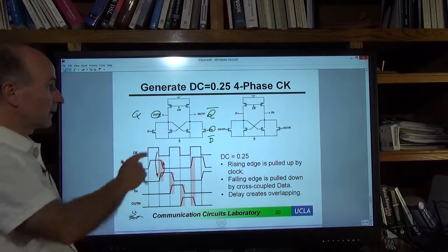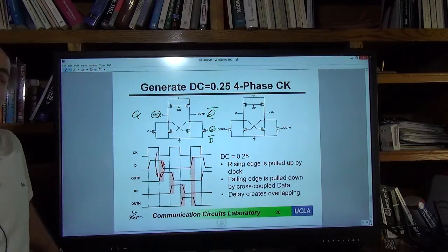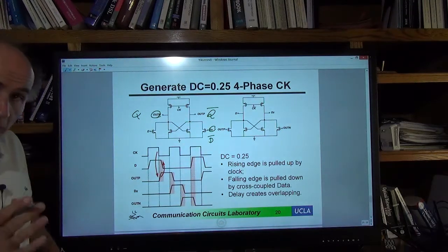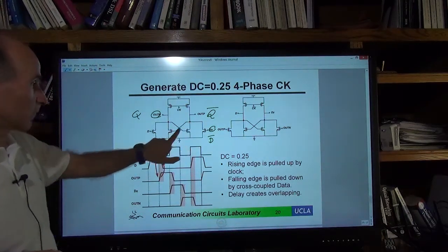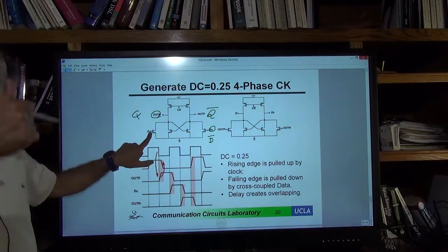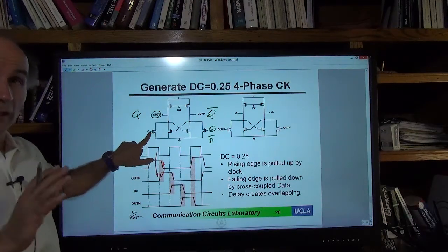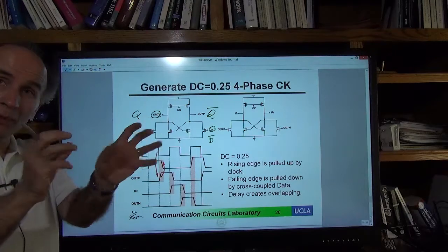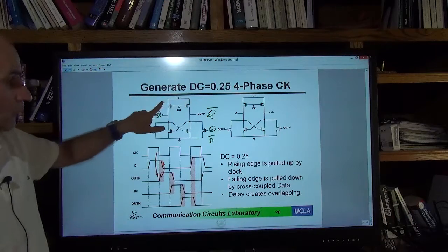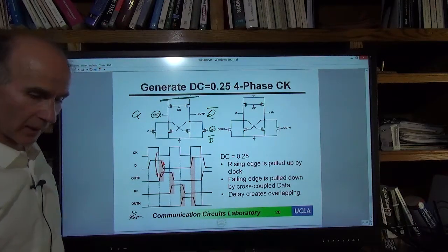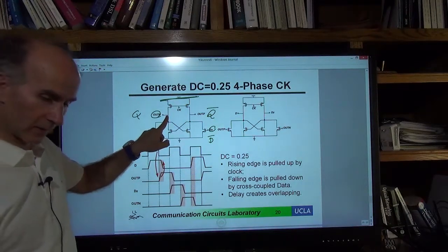Now look at the dots. Here, you see these dots actually are not quite centered. I don't know what happened. Maybe the grid was off when Yikun was moving these dots to here. So you should keep the grid on. Again, watch that video very carefully. You should keep the grid on so that these dots are exactly where they're supposed to be. Look at this dot. Obviously, this dot is misaligned, right? It's gone up vertically. It shouldn't happen. So as long as you keep the grid on, life is much easier because you don't have to zoom in and zoom out. You don't have to try to align things. They align very nicely. And again, this should be just one line for VDD, and that would be much easier. If you have dots here, you need dots here. What happened to dots here, right? So you need dots here as well.